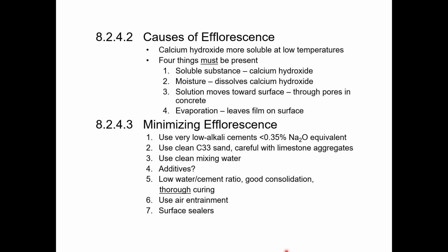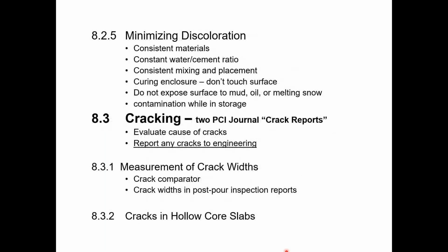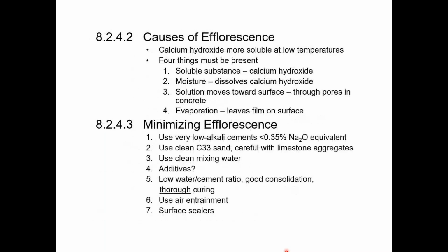One thing to think about, especially with secondary efflorescence, is once you start blasting or doing anything that's going to speed up the deterioration of that surface layer, if you're sandblasting or pressure washing, potentially you could open up small hairline cracks that were there but were covered or closed up, or even expose entrained or entrapped air bubbles that were just below the surface.